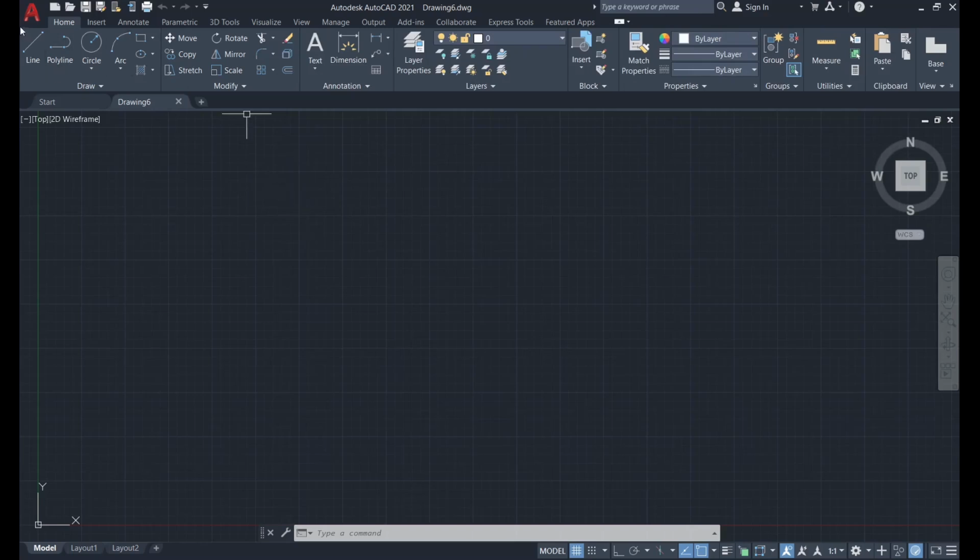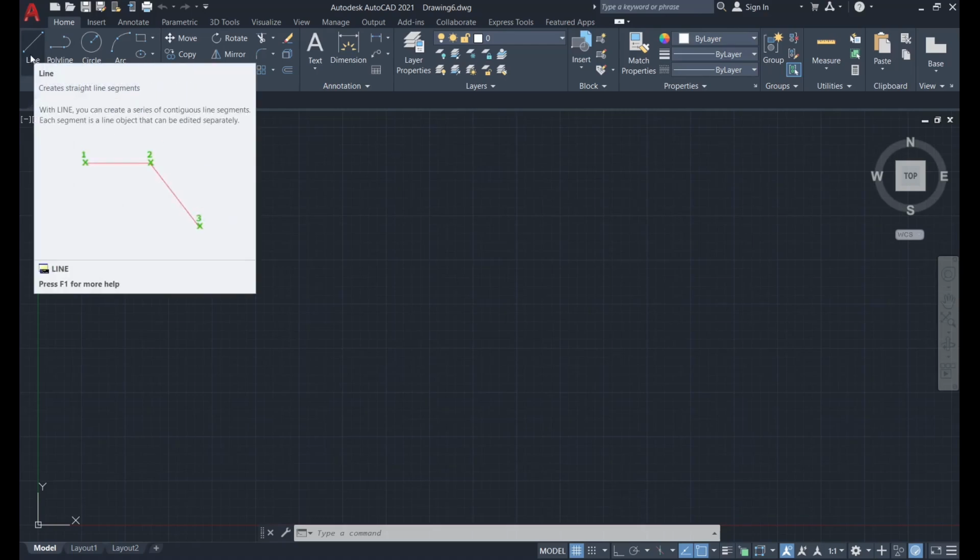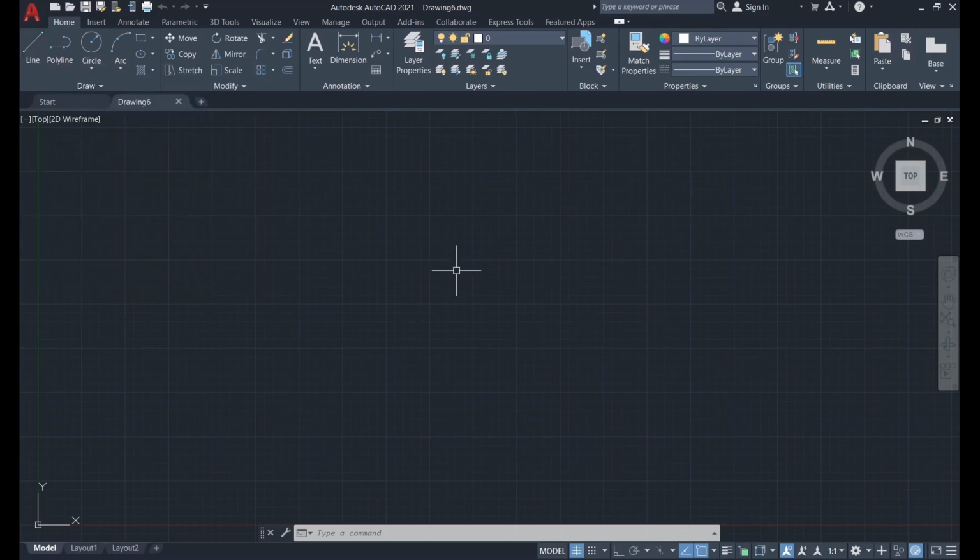It's very easy. This will be, let's say, your best friends because you can use a command by clicking on it, but as well you can use it by directly typing its shortcut on your screen. So if you are going with the cursor over it, you will see how it's called and how it's done. So this is line, so you can just type on your screen directly without touching any other keyboards, directly typing line and the command will show up.